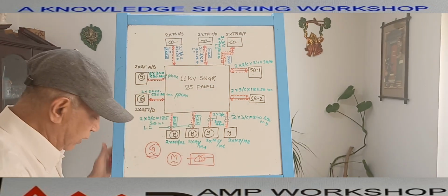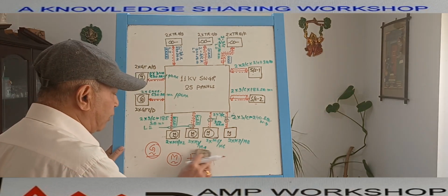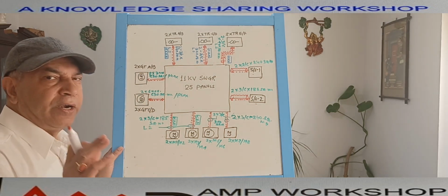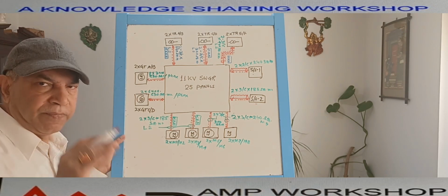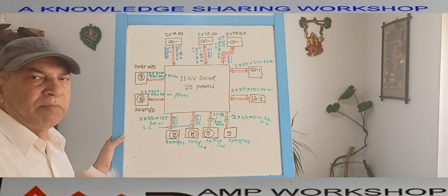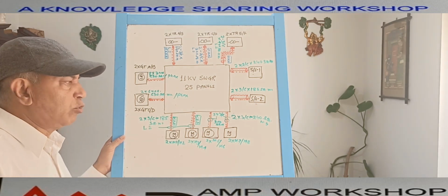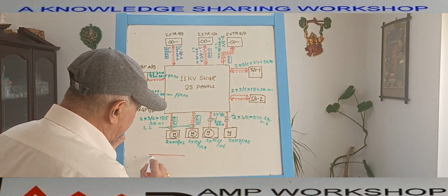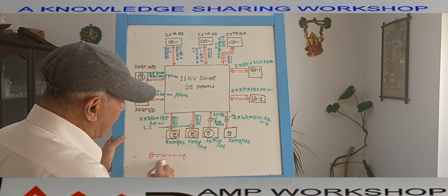In addition to this, we have used symbols for the various cable laying methods to represent how the cables are laid. We have considered 4 different laying methods. One laying method is a cable laid on the tray. It is an overhead tray or above-the-surface tray, metallic tray or PVC or GRP tray, whatever it could be. So cable laid on the tray is represented like this: this is the cable, and the dot below represents that this cable is laid on the cable tray.